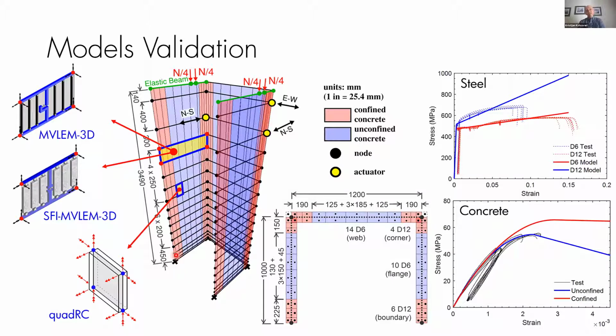If this is an industry project or practical project, usually we have some expressions to estimate the plastic hinge length of these walls, and then your element should be at least the plastic hinge length, right? It shouldn't be more than that. Then you can use a couple of elements over the height of the plastic hinge if you like. It really all depends on the size of the model, the configuration, a lot of things, but that's the general consideration. Try to estimate a plastic hinge length and then go from there.